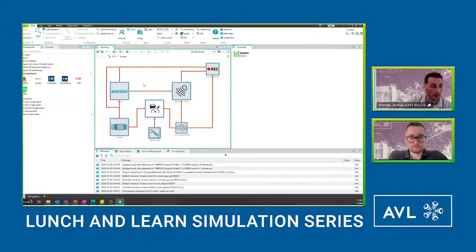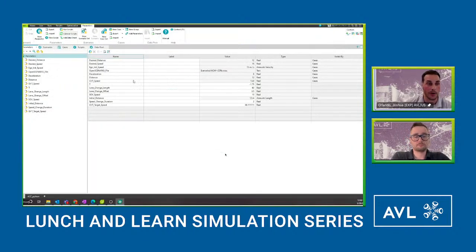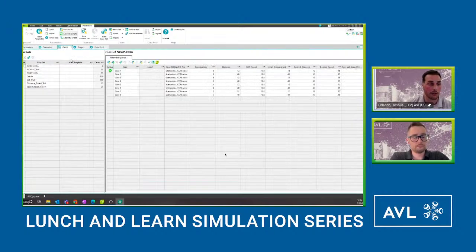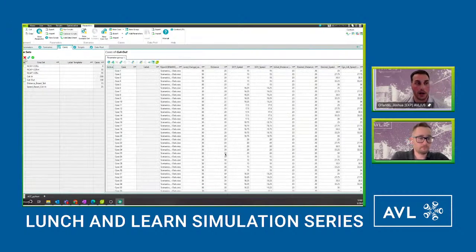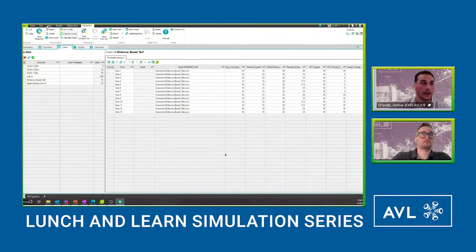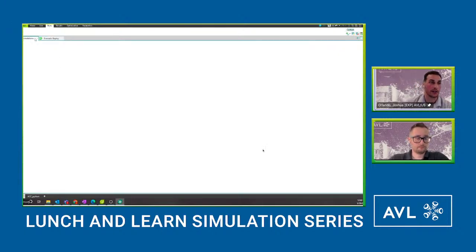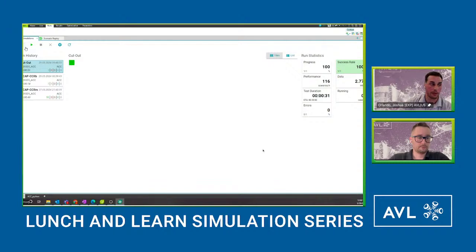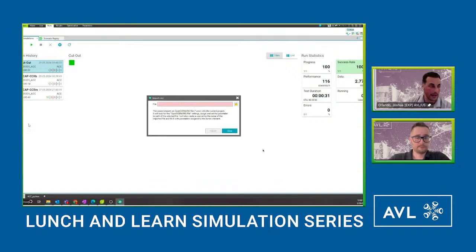Yep. So I will hop into the integration of test cases development there. What I want to do here is just get rid of what I'll be repopulating in the tool. So essentially you go directly to your runs tab. From here, you can upload a scenario directly from any OpenScenario 1.x standard scenario file.